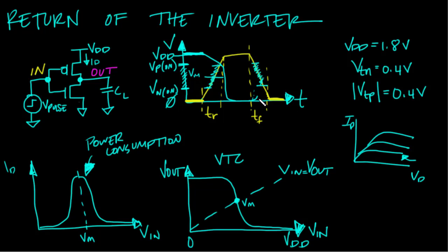But the NMOS device in this corner of the ring also is still on, and so it is trying to make sure that that node does not go up. So it's just going to be the PMOS device is sourcing and the NMOS device is sinking, right? PMOS device sourcing current at this point, so it's just going to be trying to charge up this node. Meanwhile, the NMOS device is on and it's saying, no, I'll sink everything you got, let's go. So this is no bueno until this point in time right here. So this does still look like an inverter, right? Because when the input is low, the output is high, and when the input is high, the output is low. But you see we have all kinds of guck happening here, and it takes a long time to respond.